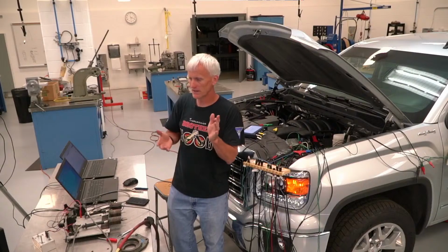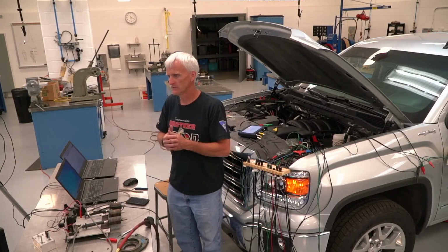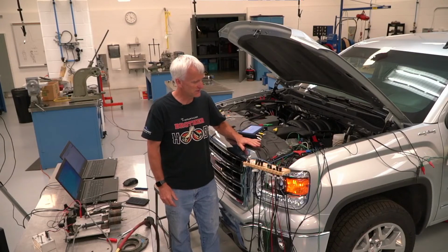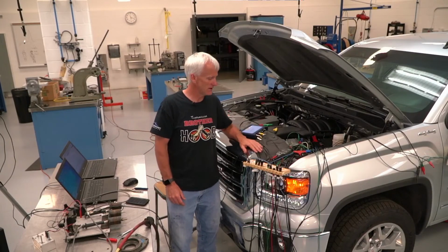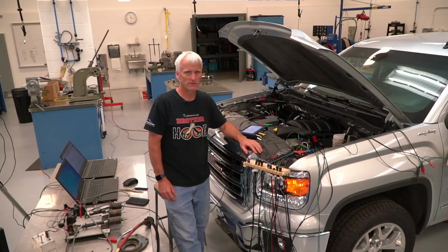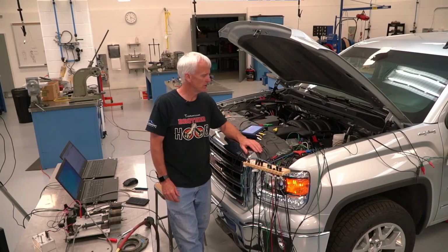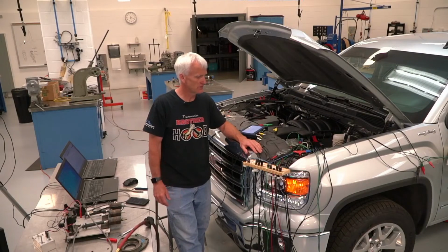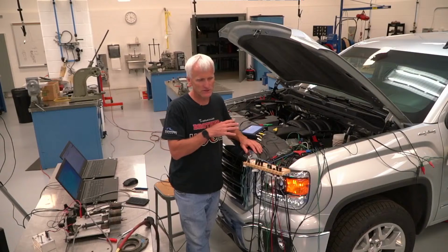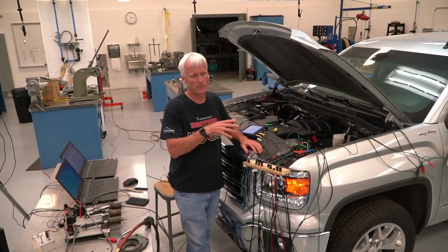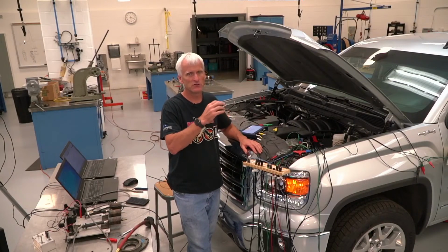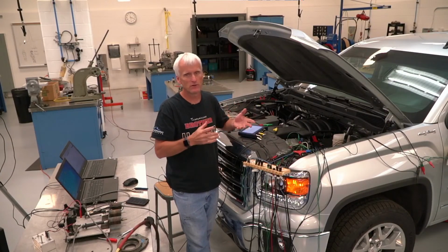And like I said, on Wednesday, I'm going to do something a little bit on the stability control, probably look at this truck, look at a yaw sensor, and go through some of the special functions they have with the scan tool. It's nothing too crazy or complicated, but they do have a pretty neat little process. It's kind of confusing the way the wording is, but if you have a wheel up in the air and you go through the process, it will activate these solenoids, and you can check to see if the solenoids are doing their job.